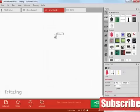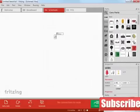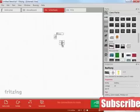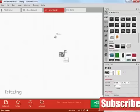Next, we'll need some kind of power source. We'll use a battery. And most importantly, we'll need a current limiting resistor. The battery is capable of generating more current than our little LED can handle. We have chosen a super bright LED that will be happy with around 28 milliamps of current. Most LEDs are happy between 10 and 15 milliamps, but check the spec to be sure for your particular LED.